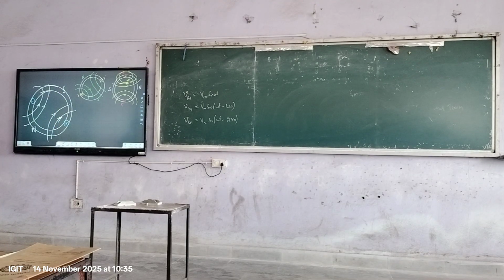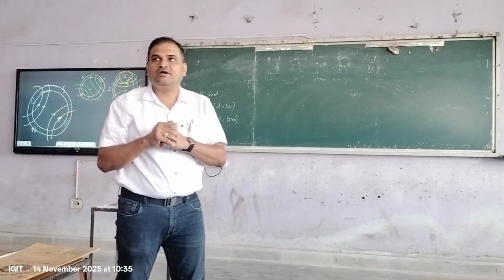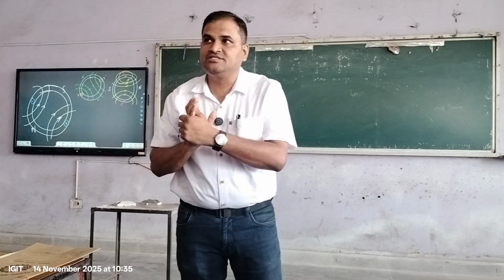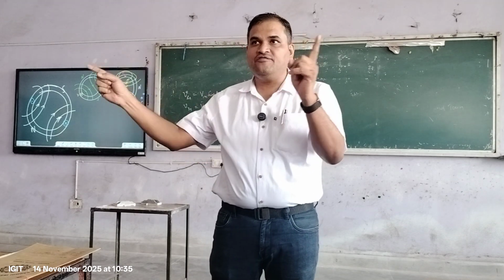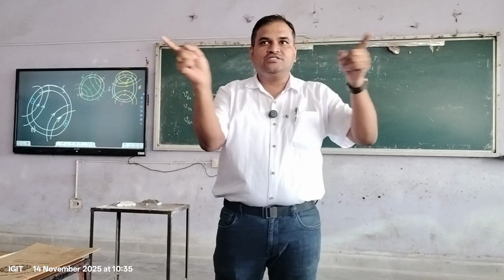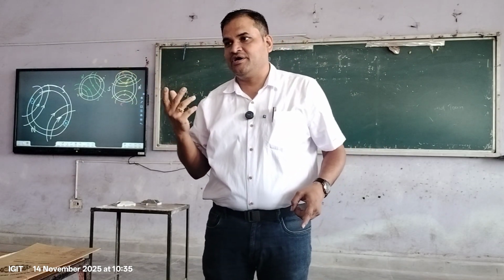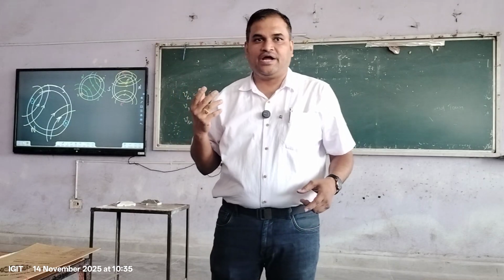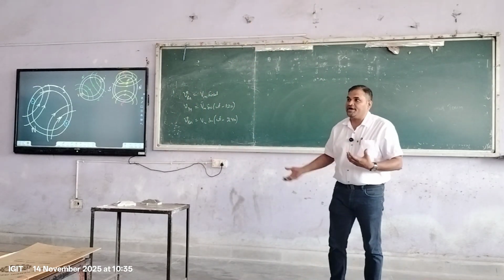Agreed? The point of telling you all these three things is that if you just give R phase, and Y and B are not with you, you are just going to get a north pole which is oscillating like this. If something oscillates like this, it will not be able to give force to the conductor. It cannot rotate the body. You cannot get a rotating flux.